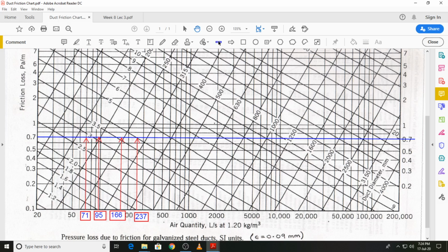So that is what we have over here. You will have a line like this showing the velocity, and this is 3, this is probably 3.25 over here, and if you draw it properly using the right scale, you might be closer to the 3.25 value, but again if you use a value of 3.2, that is acceptable. And now that completes our column for the velocity. The remaining calculation is straightforward. You find out the area, and based on that area you find out the diameter or the duct sizes for each of the 5 segments.